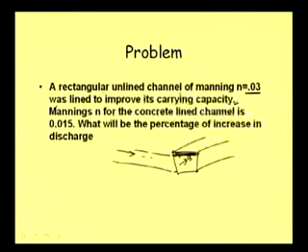Here you will have a higher depth, there less, so the flow will get retarded in this part also. So once in the main channel you have higher depth, then on the side channel also you will have water with a slower flow, and you can have a flooding situation in this part also, as the water is not getting released quickly.